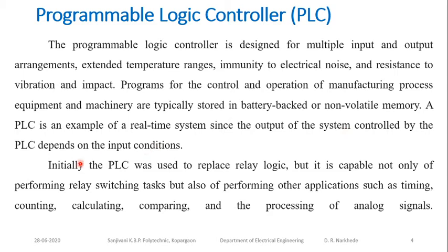Initially, PLC was used to replace the relay logic, but it is capable not only of performing the relay switching task but also of performing other applications such as timing, counting, calculating, comparing, and other processing of analog signals. So, in the initial days, as we have discussed, PLCs were used to replace the relay logic. When I implement the logic using relays, it requires hundreds and thousands of relays, which makes the wiring very complicated, and it is quite difficult to make changes in that system. So to simplify that, we came up with the programmable logic controller.